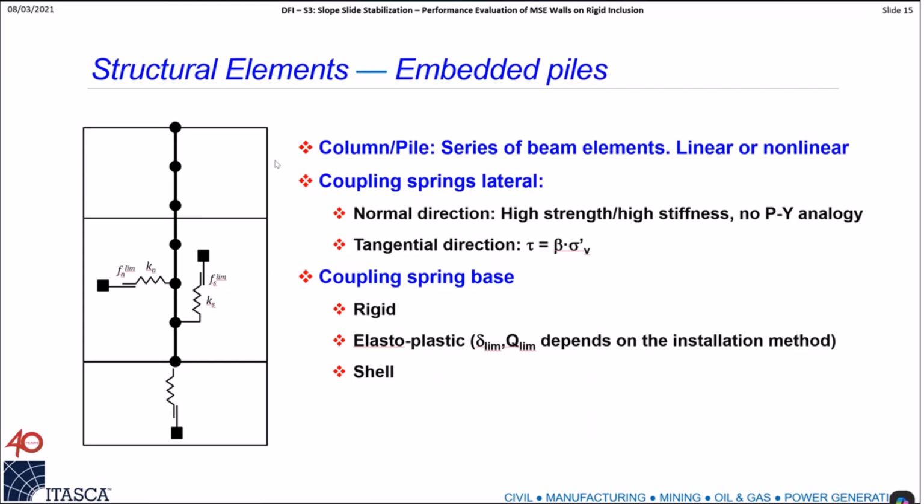So this is our domain of analysis. This is our pile element. This is an embedded element, so it's volumeless. It's based on the beam theory. It could be elastic or nonlinear. And now we have also the possibility to model this pile as a concrete element. So this is just a parenthesis. And then in these nodes, we have to connect essentially the pile with the zones, with the domain.